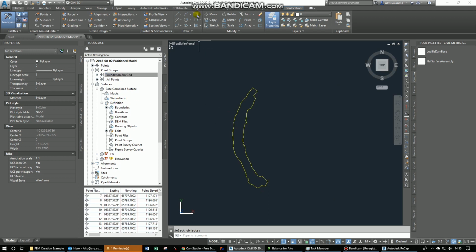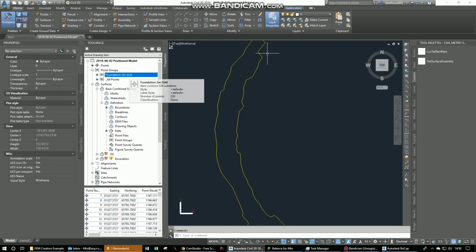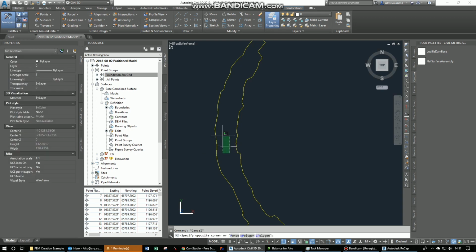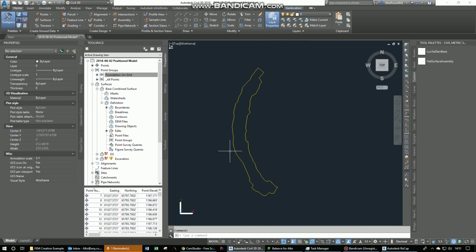Now as we move further away from the model, we would like the mesh to be less refined, but in this case, since we wanted the foundation to be relatively coarse, 2 meters we consider coarse because the width of that excavation is, as you can see there, 13 meters. So that's relatively coarse, but the FEM guys that will be working on this specific model requested that we've got a 2 meter grid spacing over there, and then a 1.5 meter spacing just on the outside of that.